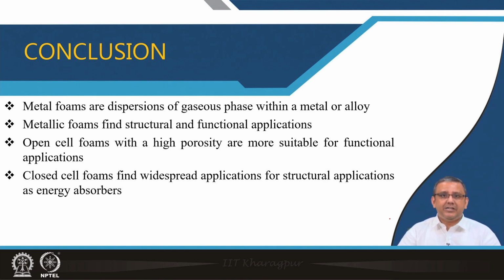They have many structural and functional applications, and depending upon the application, the foams are used either as open cell foams with high porosity for more functional applications, or closed cell foams with more closed porosity for more structural applications, mainly as energy absorbers.